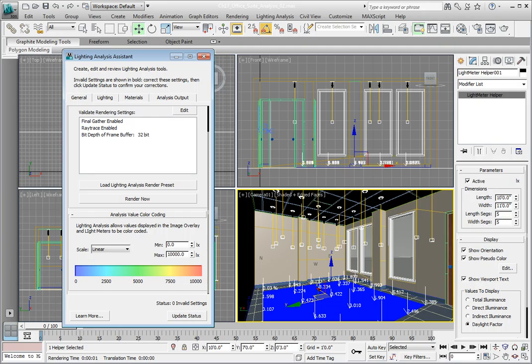However, for the maximum value, and this is something very important to remember, the daylight factor is a percentage. Percentages with mental ray go from 0 to 1. To set the value to a percentage, in this case 11%, enter 0.11 into the maximum value and press Enter.